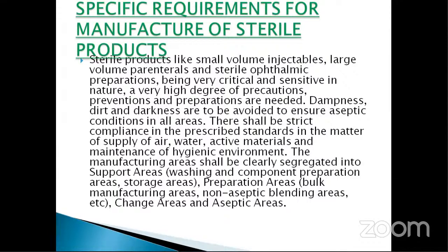You see, there will be strict compliance of the prescribed standards in the matter of supply of air, supply of water, and obviously the active materials and the maintenance of a hygienic environment. The manufacturing areas shall be clearly segregated into support areas, that means where washing and component preparations, etc. are done. The preparation area where the bulk manufacturing preparation is done and non-aseptic blending or mixing is done, etc. Then change rooms. Change rooms means the rooms at the entry place, provided for changing the outside dresses and taking the factory dresses.